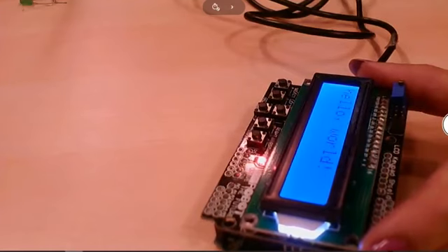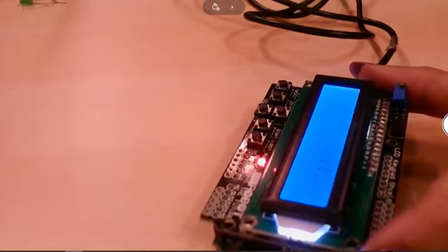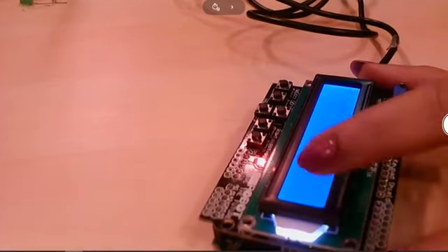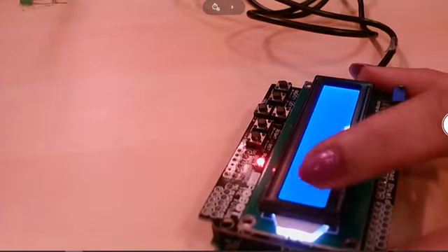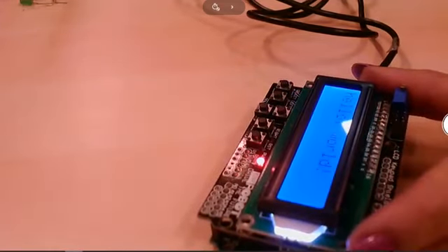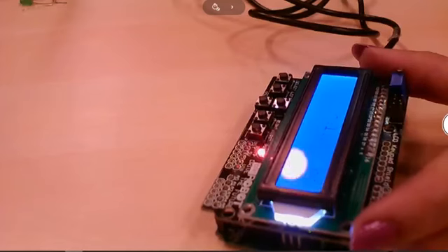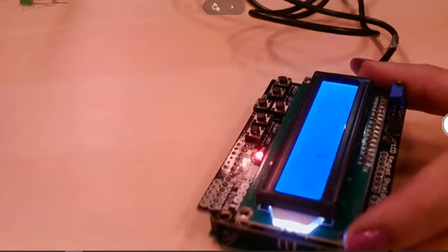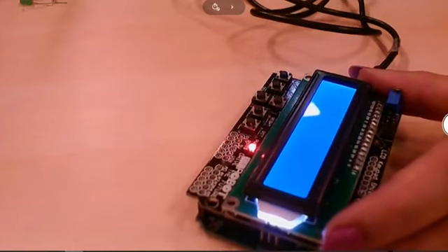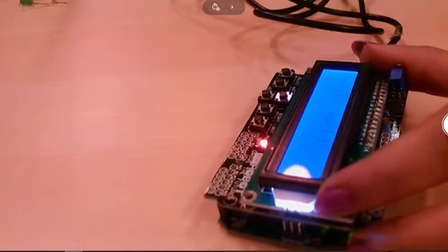So, you can think of an on-field POC you are developing, let us say temperature is getting sensed, and at a remote place that device has to be installed and the temperature has to be monitored continuously. So, you can have an LCD display wherein the DHT11 sensor that I showed you, whatever temperature we sensed, that can be displayed continuously here. So, the on-field device need not be connected to the laptop every time. If it is being powered by using a power jack, you just have an individual component and the entire circuitry developed as a POC connected to the in-field device, which will keep displaying this.